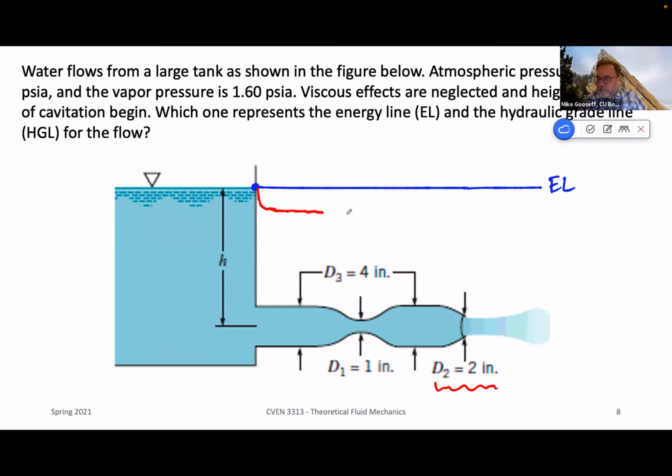But what this means then is, when we get here, so V1 is greater than, let's do it this way. I don't like their numbering. Let's call this A, and this B, and then C. And for the sake of completeness, I'll call that D. So VA is going to be greater than or less than VB. What do you guys think? Less than, right? Because it has the larger diameter, larger area. So VA will be less than VB,